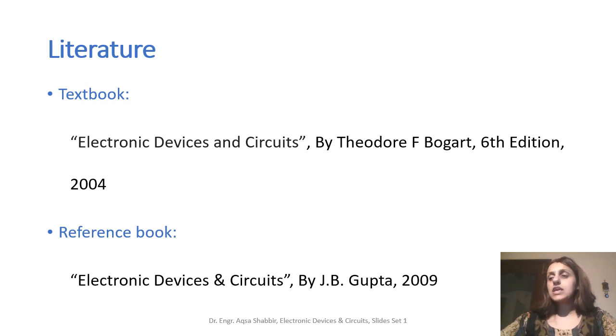And then lastly, we saw that the temperature coefficient of resistivity in case of semiconductors is negative, meaning that when the temperature is increased, the concentration of charge carriers increases inside semiconductor materials, and that leads to a reduction in resistivity. And this is a behavior which is opposite to what actually happens inside the conductors.